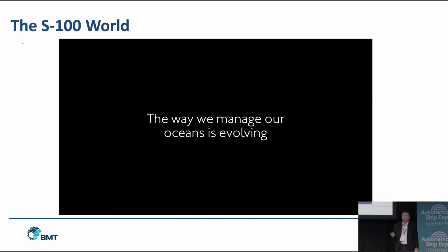At its foundation, the S100 framework is a series of machine-readable product catalogues that allow data standards to be updated and active systems to be updated very quickly going forward. We've been working principally in S102, which is ultra-granular bathymetry; S104, dynamic water height; S111, surface currents; and S129, which is the next generation of uncrewed clearance management.